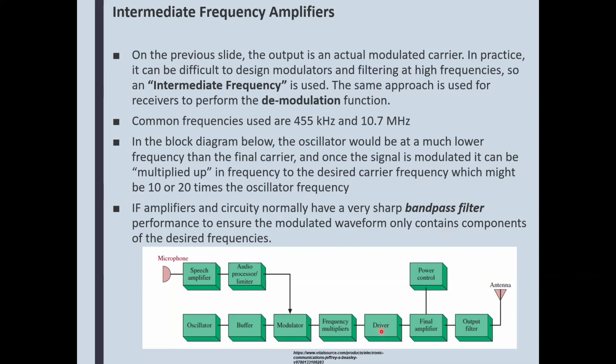Then there's a driver. A driver is an amplifier that takes a smaller signal and makes it a little bigger, or a lot bigger. So there's the final amplifier, and there's a driver that supports it. Here's a very low signal. This one boosts it up, dresses it up, makes it a little more meaty, and then shoots it into the final amplifier. The final amplifier takes it and makes that thing really strong, filtered out.